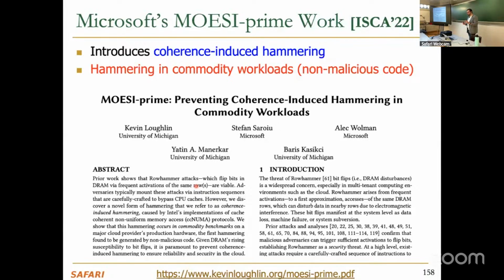So this is really something that, once you're implementing that kind of protocol for cache coherence, it's hard to think about its effects on the memory, like RowHammer, right? And it shows that this design slipped out somehow, and it's actually in the wild that this MOESI protocol is causing some hammering effect on some rows, and it can be exploited. But luckily, this paper shows a better design or better implementation of the MOESI protocol, and it solves the problem already.